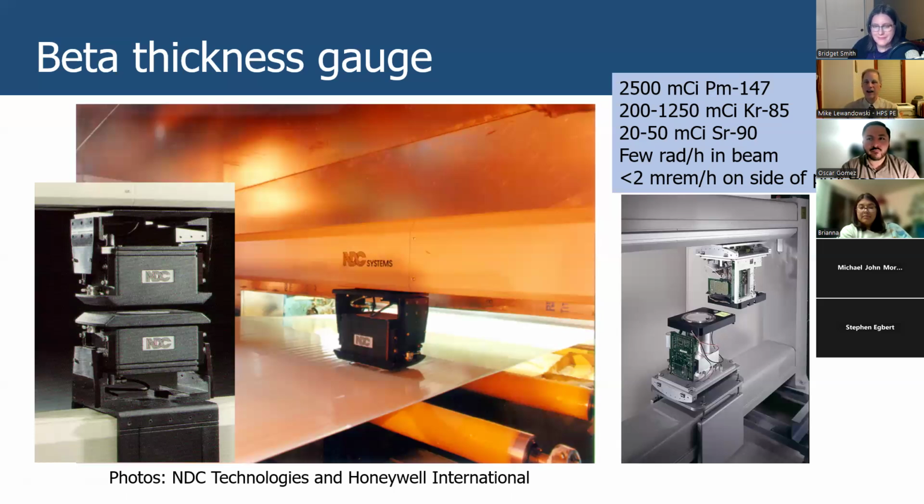And then we can tie this equipment into the coating head, the part which is releasing the material that's being coated on our substrate. And that can happen in an immediate situation where there's no longer a time lag between taking our sample, determining its thickness, and then providing feedback to make an adjustment. All that can happen immediately.